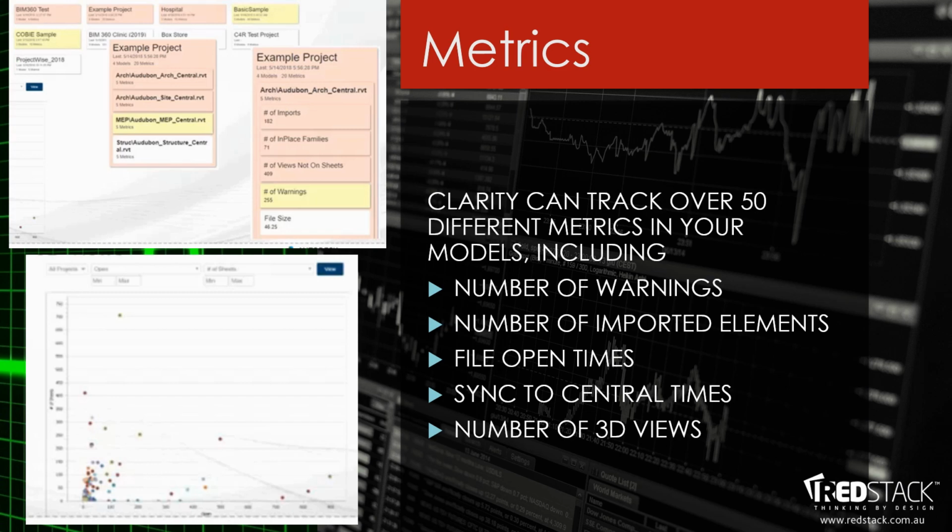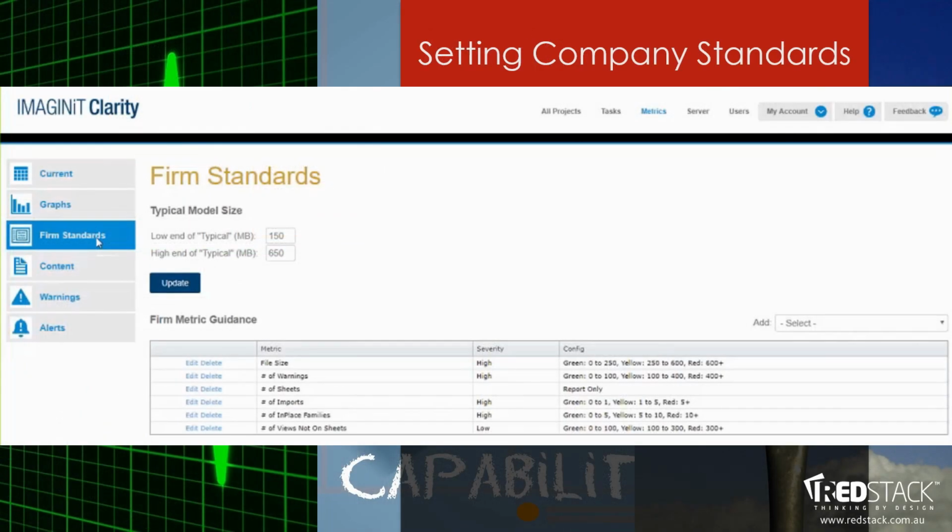So what you can set up in Clarity is compliance, setting up company standards. In this screen grab, we've got a typical model size between 150 and 650. If it gets over 650, it's going to highlight it. Here we've got file size, number of warnings, number of sheets, number of imports, and we can set some standards in a traffic light system. And at any given time, or any given day, we can see how our projects are performing.